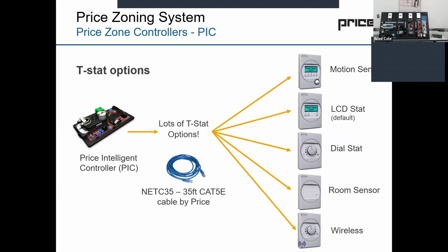Contractor can set up the MAC address or the BACnet addressing as needed. And then it's also a thermostat. And there's service menus that you can get into to change parameters on site if needed, like min and max airflows, balancing, damper position, for example, output configuration. All of this can be changed right through the LCD thermostat.